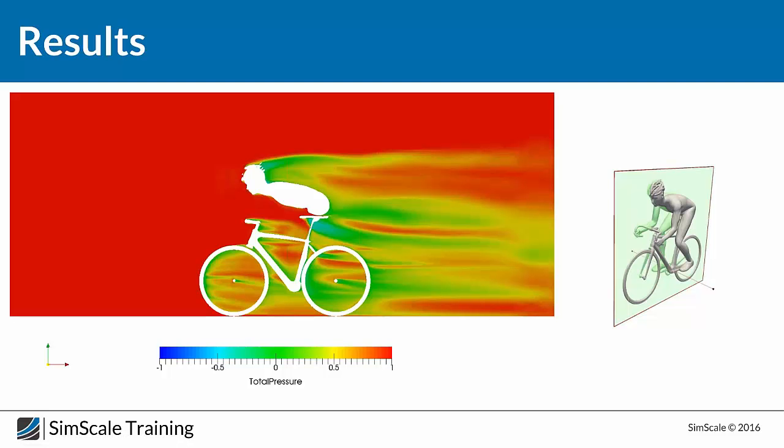And first of all, yes, we considered rotation of the wheel, so we used a special boundary condition, which is applying a rotational velocity on the surface of the wheel. That's the reason, for example, why you have these flow structures inside the wheel: you have a higher flow velocity outside than inside the wheel, and this will produce vortices, which then create this disturbance. And in this image you can really see the effect of the rotational wheel due to the flow separation and pressure fluctuation effects inside the wheels.